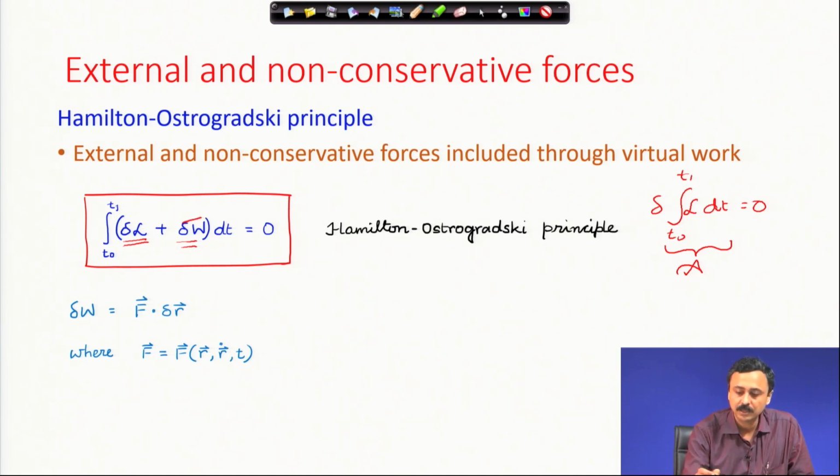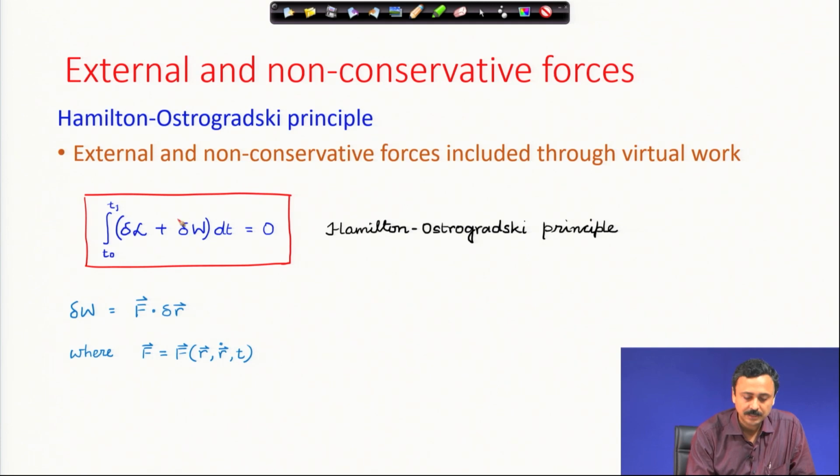Just like we discussed in thermodynamics, dW, here it is delta W, this is a single expression. You cannot pull out this delta. Therefore, this is not a variational statement or a variational principle. Hamilton-Ostrogradsky principle is not a variational principle. We cannot write delta of some integral is equal to 0. No, it is delta L plus delta W, a composite thing. We cannot pull out the delta, it is not the variation of a scalar function.